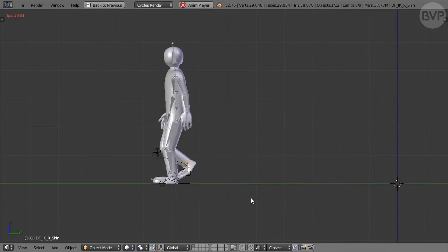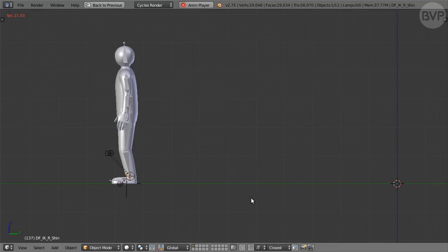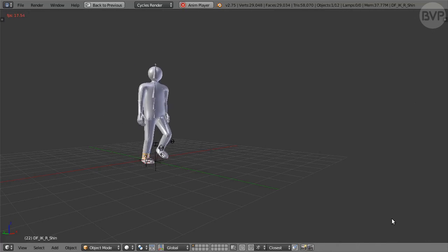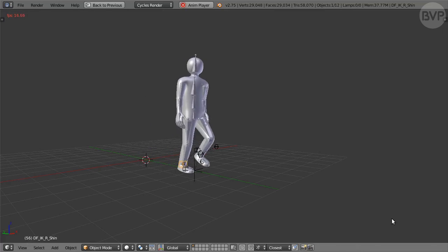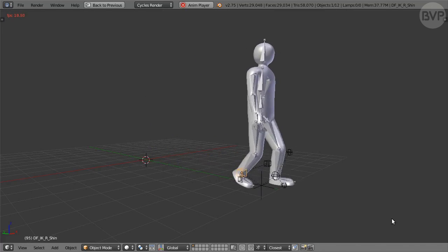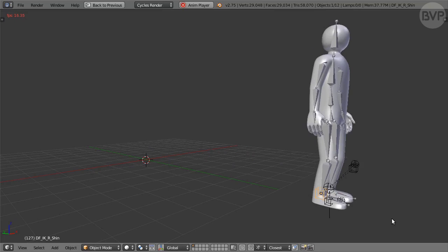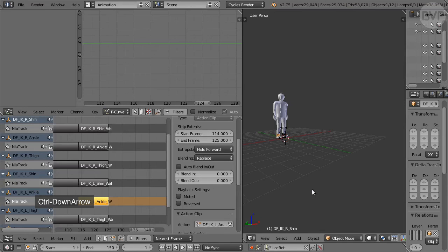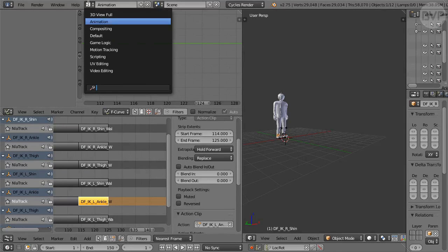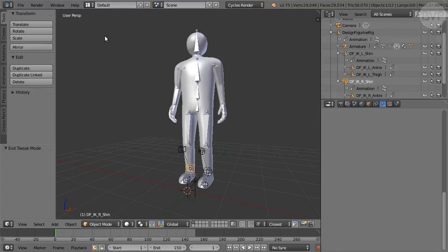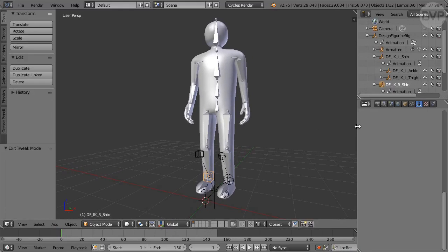Great, now you know how actions can be cycled and combined with other actions for a longer animation. One last thing. As stated before, the best way to use this figurine is with accessories and props. So, as a final quick lesson, let's place a very simple hat on the figurine's head. From the screen layout menu, choose Default. Make sure Tool Shelf is visible and disable automatic keyframe recording.